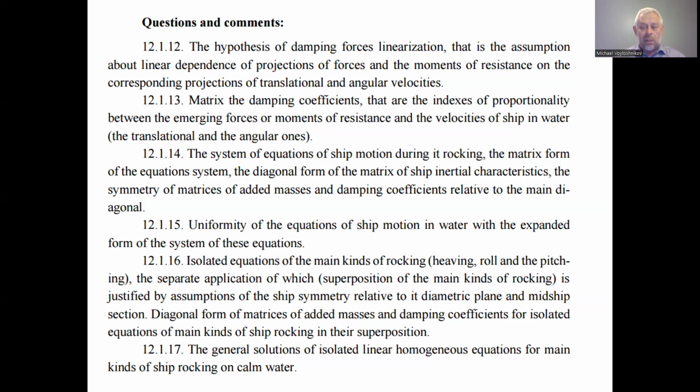And we have the second row in each equation of the damping forces, so forces of resistance arising in each direction on behalf of the velocities in all directions, all six, three translational, three rotational. And we have the third row in the equations of the restoring forces, which is only for the main types of rocking.